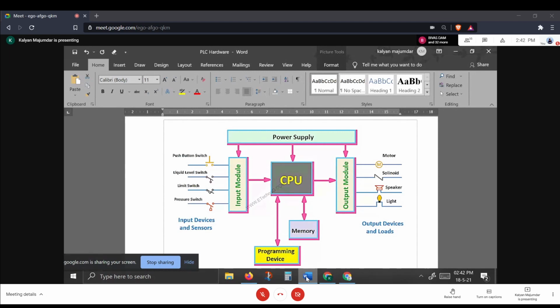So that is what makes a PLC different in terms of hardware compared to either your laptop or a smartphone, because a laptop or a smartphone is not designed to connect to input signals or output signals. Of course, you could connect your laptop or computer to a switch, to an input signal, but for that you need additional hardware.